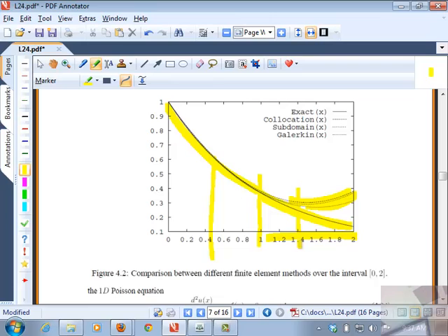Yeah, I guess for those in the PI, the question that we are discussing is, is it better to take a higher order polynomial that's global, or to take lower order polynomial in each sub-region? That is the driving force for the finite element. And Aaron's point of view is that you should take lower order elements, but more elements, that will give you the greater accuracy. Right? That is generally true, and the other advantage that you have with breaking it into smaller elements is you can fit more complicated geometries.